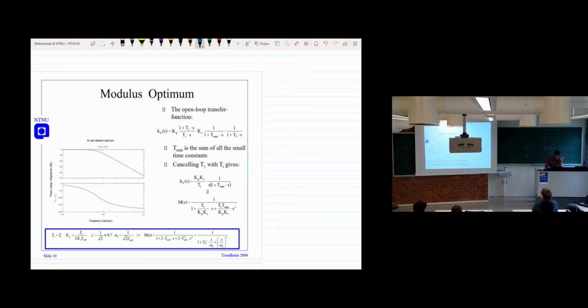So we have the PI controller. The first part is the PI controller, and the last part is the process, the plant. Maybe we can move the Ks here also. This Ks maybe assumes the power stage. Then you have the controller, the plant, and we have another function here, 1 plus T-sum S.